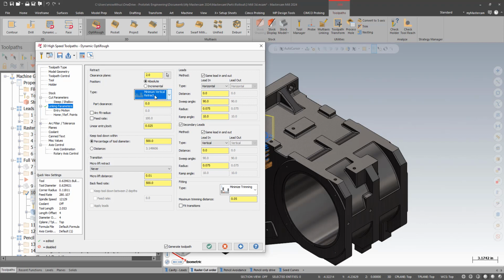It figures out the minimum distance it needs to pick up in a straight line, but many machines dogleg. So for instance, if I go from 0, 0 to X4, Y10, most machines won't go in a straight line move. It'll go X4, Y4 at a 45, and then finish out the rest of the move to Y10. Many machines, when in rapid, move the axes at maximum rate simultaneously, so you don't get straight line moves. Well, it figures out how far to pick up in a straight line move, so that can get you in trouble. So this is kind of dangerous. If you turn these on, where I'm going with this is you want to make sure to also turn on feed rate, or eventually it's just going to burn you. You're going to get in trouble with it.